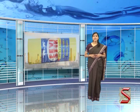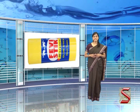Adhesives are also mixed with plasticizers, wetting agents, etc. You will find different kinds of adhesives in the market, and usually such commercial adhesives contain a mixture of 2 or more adhesives. While natural adhesives are cheap, water soluble and mostly used for paper, synthetic adhesives are expensive, water resistant and used for woodwork, plywood and lamination purposes.